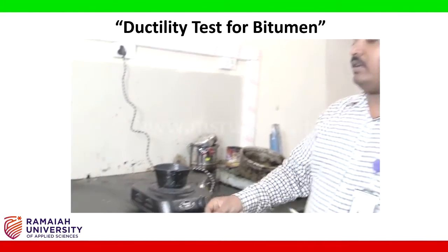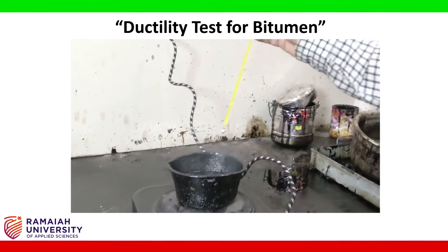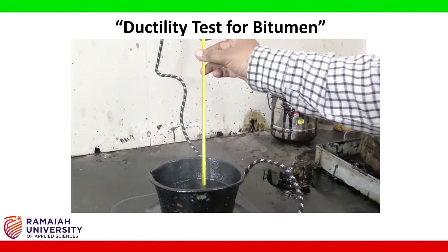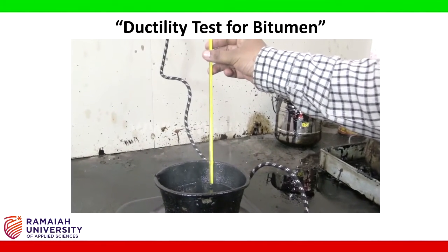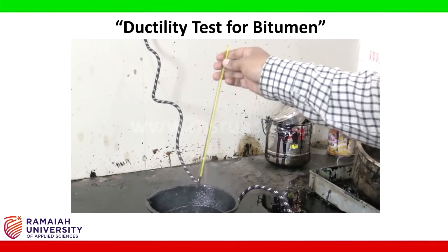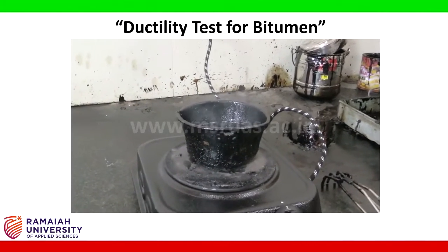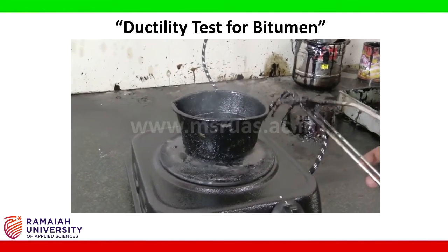So make sure that the bitumen is attaining the pouring temperature. You measure the temperature of the bitumen, it should be around 125 degrees centigrade. After attaining the pouring temperature, we are going to transfer the bitumen to the briquette mold.